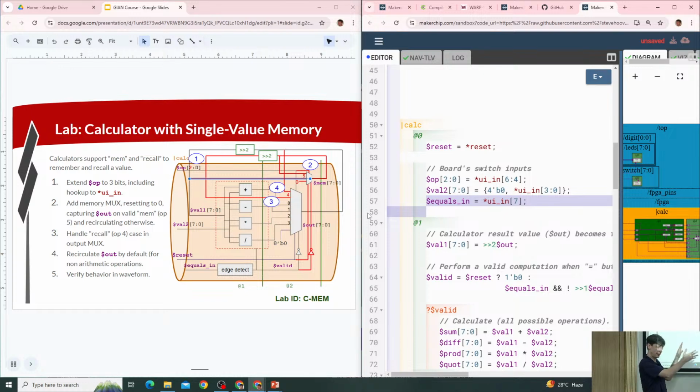So if you have a 5-stage pipeline, just to repeat for the remote folks, if you have a 5-stage pipeline and you have a reset, the methodology that I'm recommending, you're going to use a dollar reset. It's going to take 5 cycles for that to march through the pipeline. That's fine. The reset transactions, if I can call them that, that we've created are going to march through the pipeline, and as they do, they're going to clear their state as they go along, clear the state of the machine. You release reset, and now you have the opportunity to inject a valid operation in the front of the pipeline. So you've got these reset operations, and then here's your first valid one.